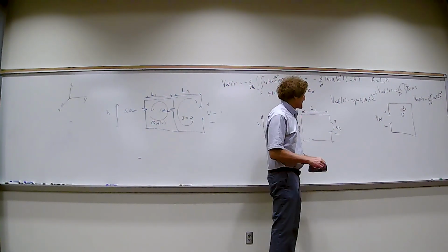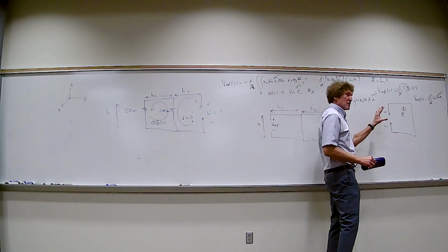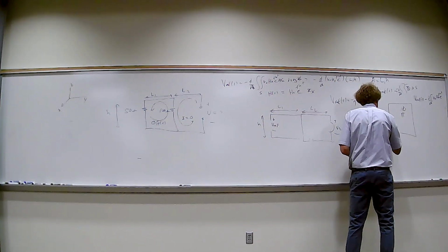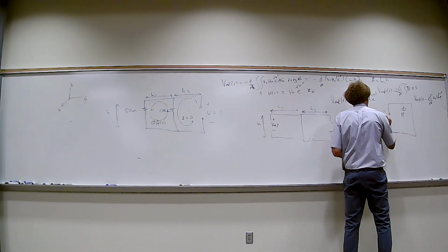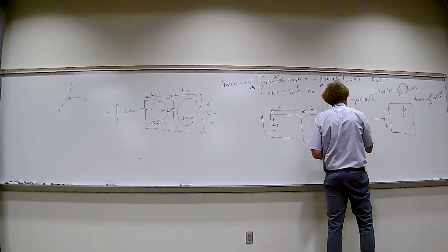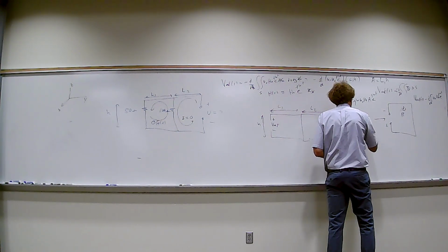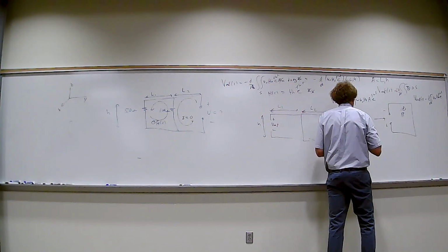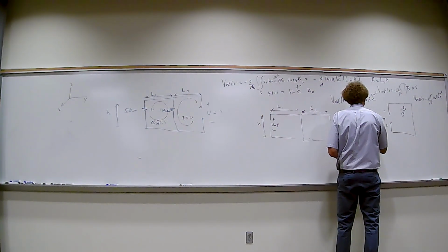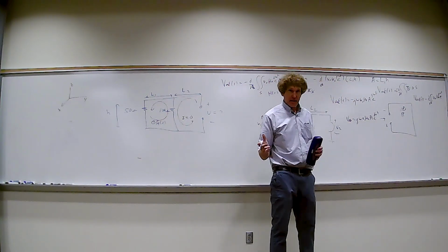So what I do now is I say this actual VEMF, I'm going to reverse the signs. And I'm going to say this is going to be positive and this minus. And the value of this voltage right there, the open circuit voltage, right here, I call it V open circuit, is just going to be j omega mu 0 H naught times the area times e to the j omega t. Can everybody follow me on that?